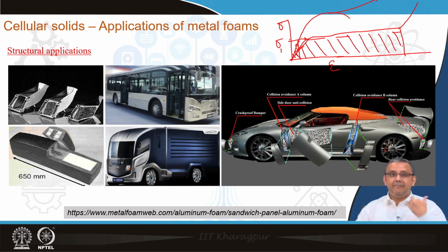So, that means the metal foams can actually be used as sacrificial components. They will crush, and while crushing they will absorb a significantly high amount of energy, but while doing so they will protect the valuable component of the car and also the inhabitants of the car inside the automobile. So, this is the reason that these metal foams are extremely good for crash protection applications, and this is often exploited for automobile design for advanced automobiles.